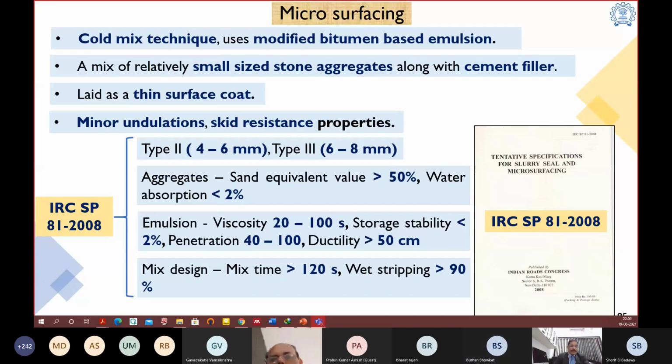A lot of work is going on in the utilization of slag currently in India. Hopefully, warm mix additives are another area which, if we want to increase the use of RAP, WMA has to come up. Some work has been done on highly polymer modified binders, and other things are also in practice as of now in India.